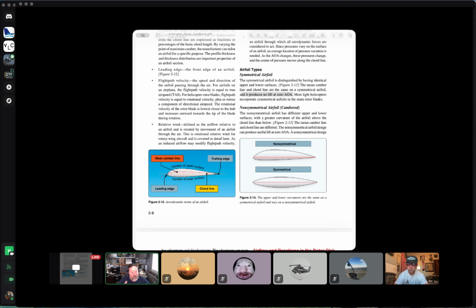On the Bell 206, the way that the servos are set up and the way that the collective mixer is set up is done differently, so that you have to actually check the collective, because it has its own servo, right? You have to check the collective and move freely. So you do this little 1-inch lift of the collective, hydraulics off. And of course, if it was generating lift, that would be a pretty dangerous place to even start at. Right.